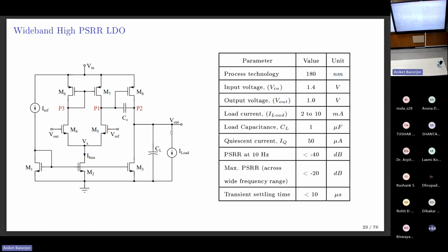When we follow square law, we have to meet this table. If we follow square law to come up with our WLs, that will lead to some specifications not being met, or we'll go through 3 cycles of iterations to meet this table in the end. So we are going to avoid those iterations by following the lookup table based approach. The ultimate goal is to come up with WLs of all these transistors, M1 to M8.